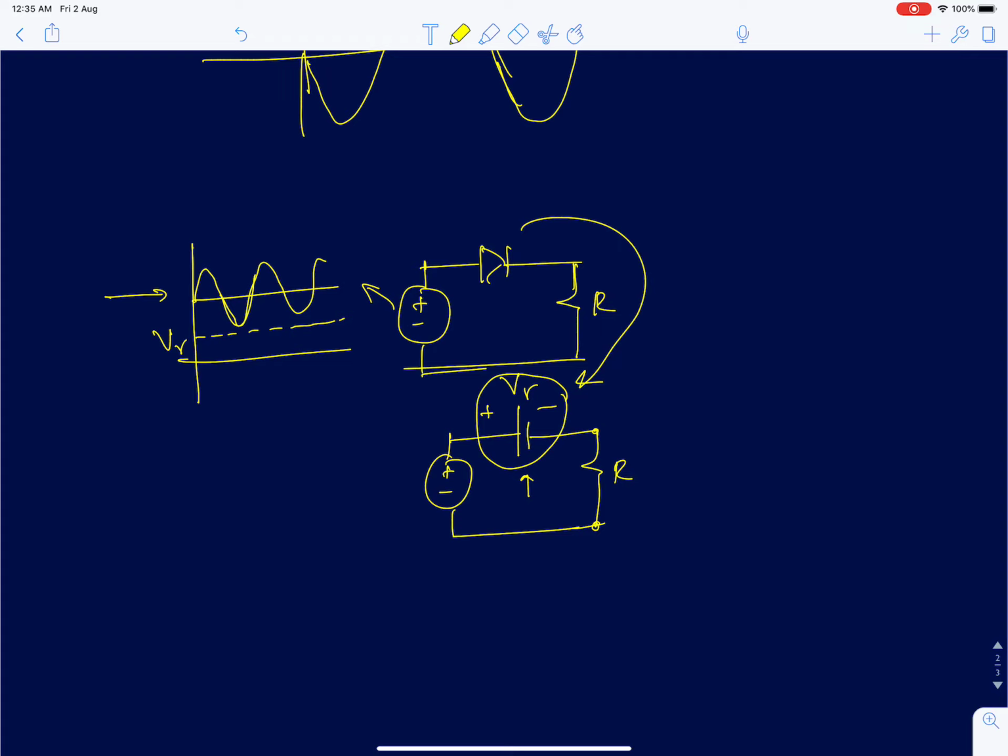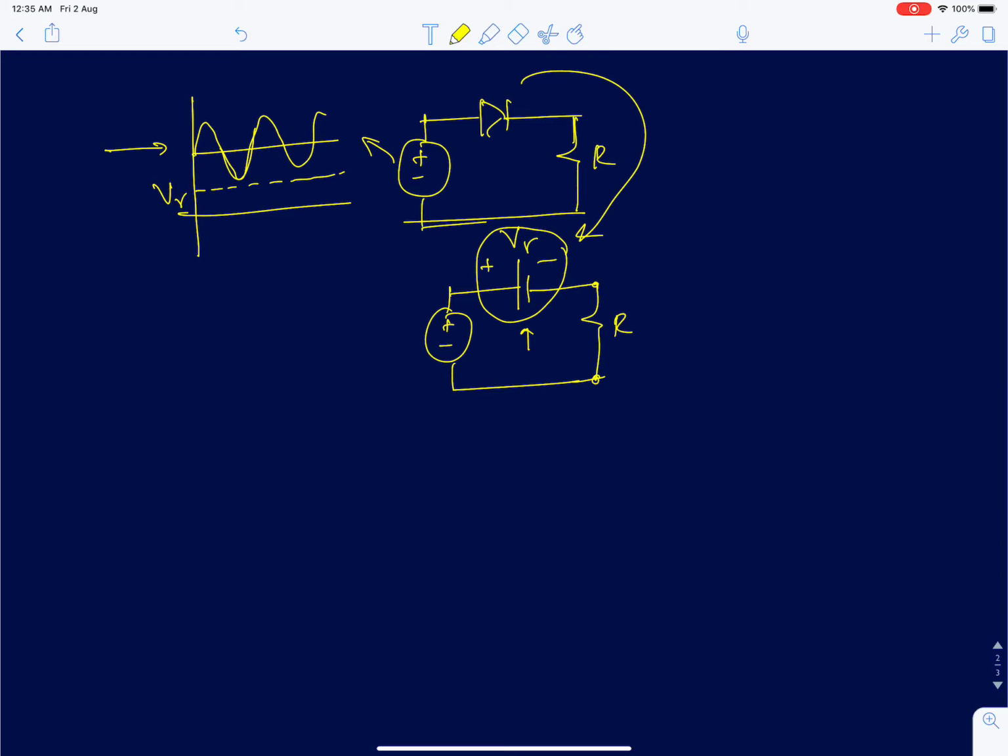So just to refresh your memory, what is AC power? If I have a sinusoidal signal, V cos(omega naught t plus phi), fed as a voltage input to any two terminal device, and the current is going to be Ip cos(omega naught t plus phi), again we know this phi can be plus or minus pi by 2 depending upon inductor or capacitor. For a resistor the phi will be 0, both the current and voltage will be in phase.